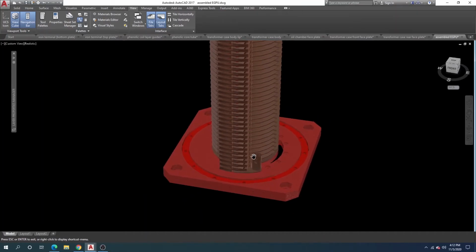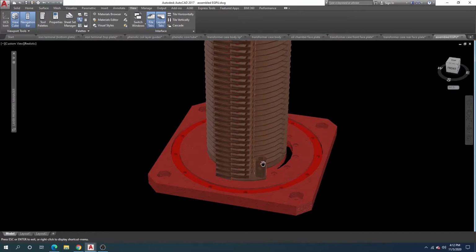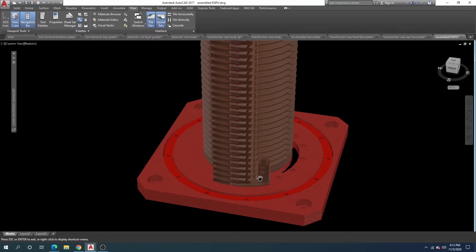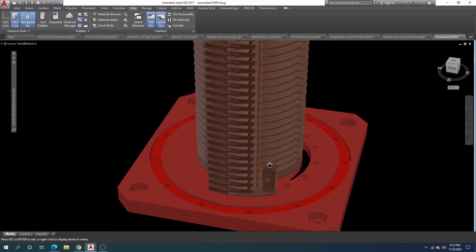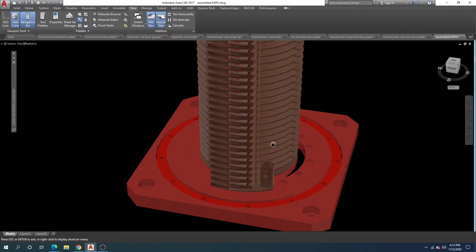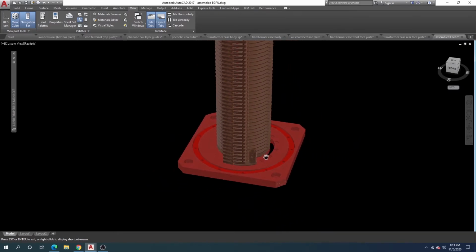That's why these terminals are designed like this, because this is where the zero gauge copper wire goes, and zero gauge can handle 100 amps, by the way. That's why I'm using such a large gauge of wire. So this is where the stripped zero gauge wire will be inserted. This is where the two set screws are to secure that wire. And that wire will have to go all the way up.